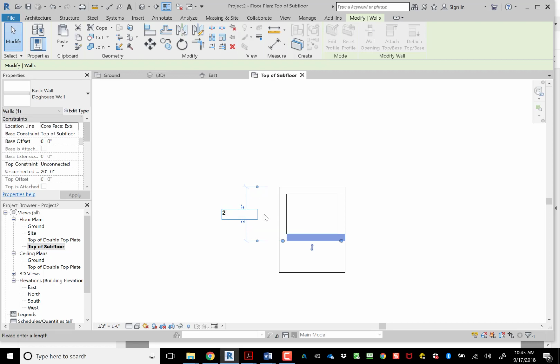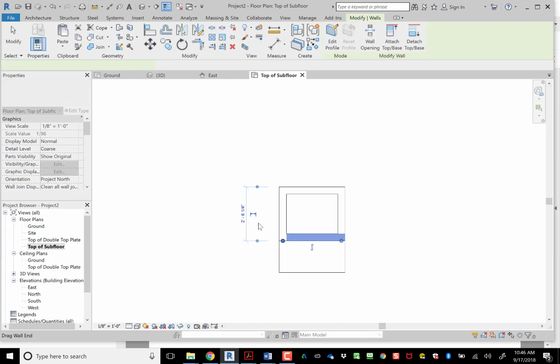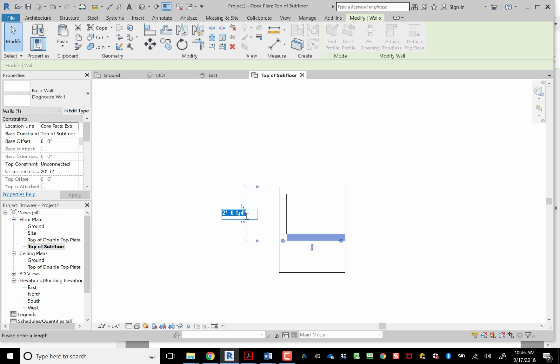When you guys are designing this, you should keep in mind the material, like the framing, because you want to save the amount of cuts that you do and the amount of wasted studs that you have. So we're doing a preliminary design. You do that in Rhino or a physical model or whatever, and then you put it in Revit, and then you lay out the framing. And then if you discover I'm 1 inch over and I need an extra stud, you make adjustments to your design so that you don't have to buy an extra stud and cut it and spend an extra 15 minutes of your time doing that.